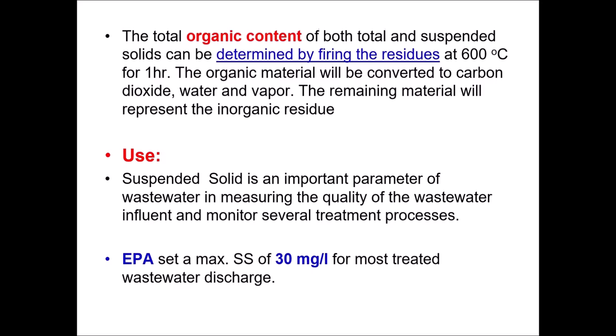We do this division for both suspended and dissolved solids. Suspended solids are an important parameter in wastewater. They are used to measure the quality of incoming wastewater and to monitor the performance of various treatment processes. Here, incoming wastewater or influent means the wastewater that enters a treatment plant before any processing. According to the U.S. Environmental Protection Agency, or EPA, the maximum allowed suspended solids in most treated wastewater discharged into the environment is 30 milligrams per liter.